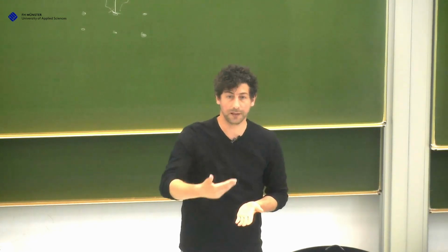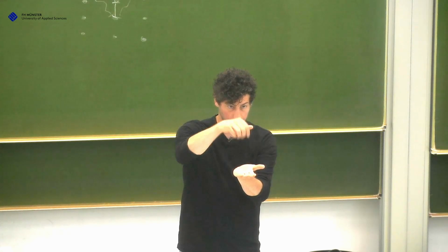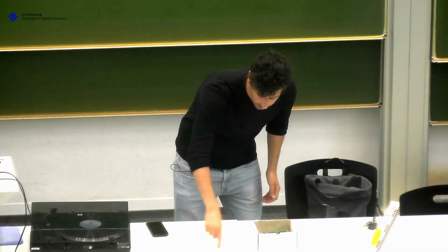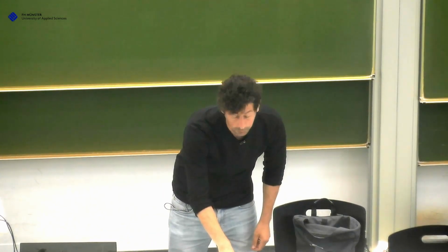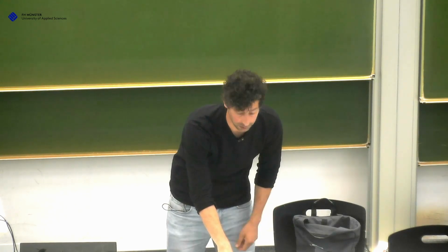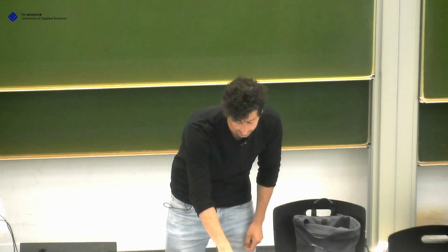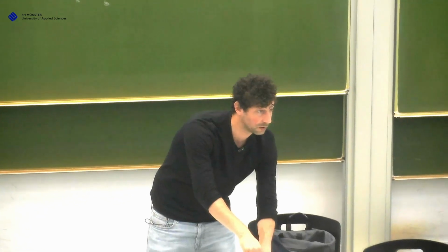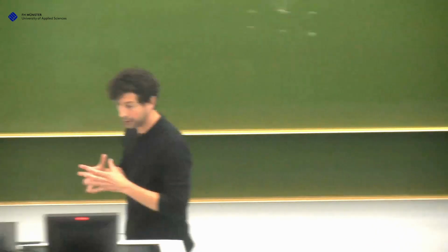And for example, you can tell the machine, I want to have a constant force between my tip and my sample. So what happens if you move your needle where the tip is sitting, and then now a bump appears? You would be too close, so the adhesion force is lower or stronger, depending on the material. And this means if you said, no, I want to have a constant force between my sample and my tip, what has your tip to do? It has to adapt to it. And then now you're losing distance, so the force is too weak, so it goes again. And like this, you can follow each kind of surface.